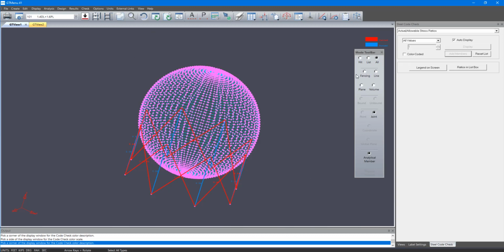And now I want to pass the support reactions to the foundation design engineer. Now, for the foundation design engineer, there's 2 things that are required. So they need to know the location of the base plates. They also need to know the reactions on the base plates, okay? So they can design the base plates and they can also design the pedestals for this tank, and they can design the flexible mat foundation for it also if required, okay?